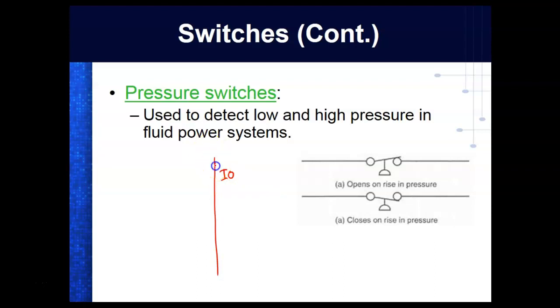So that means if I have a pressure switch, then over here you've got to use these symbols. On the side where you wire them up, we use the symbols. So I'd do that, and that means that is a pressure switch hooked up to that input. Now in my PLC program, I'll come over here and do that, right? You understand?